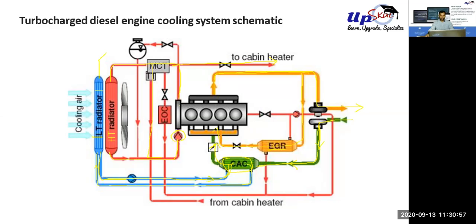Okay, this actually improves the efficiency, but at the expense of losing some power. But yeah, this is great for fuel efficiency and mileage. So we cannot just insert the burning hot gas inside the engine because it will result in pre-ignition. So what we have to do is cool it down first. There is some limit on how much to cool, but we need to cool it down.